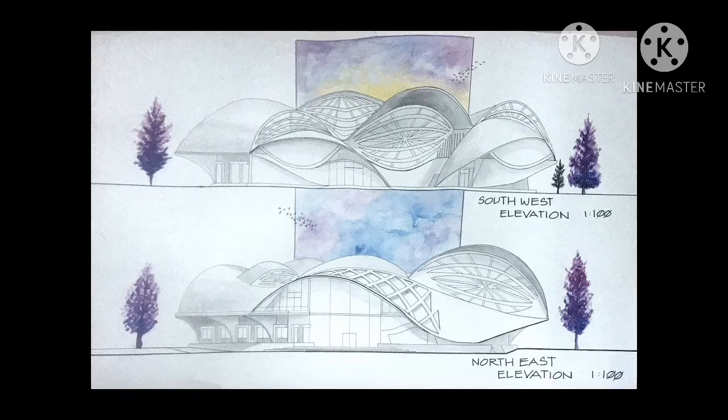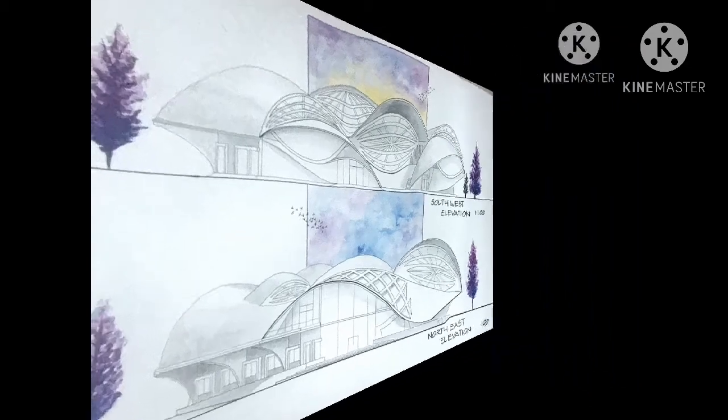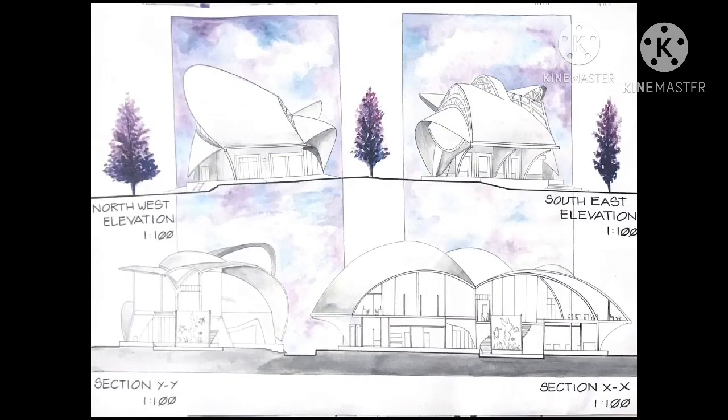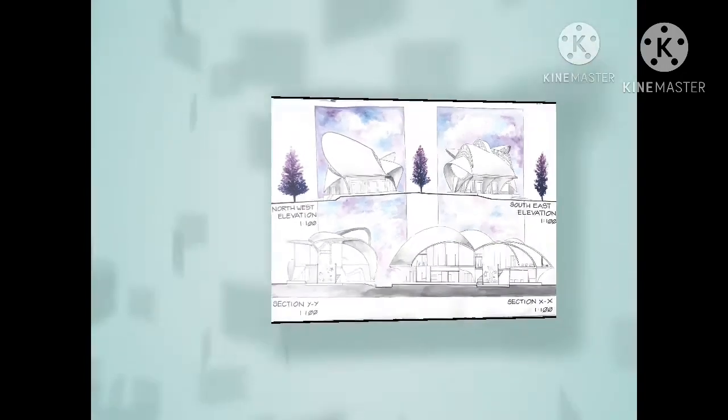Same goes to the northeast elevation. There is a bigger opening and also a smaller window opening to collect the wind during the night time. The highest peak from the first floor to the ceiling is approximately 9 meters, which is good for wind circulation, and the hot air can exit at the top window louvers. The depth of the aquarium is 5 meters, and people can see and touch the water at the first floor while enjoying the fascinating view of the sea.